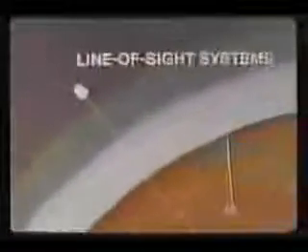For example, the operating characteristics of modern communication satellites are similar to those of the radar system already examined. Because of this similarity, their operation may be degraded by similar nuclear phenomena. The satellite uplink is somewhat less vulnerable to absorption than a radar of corresponding power because the satellite uses direct rather than reflected energy. The downlink, on the other hand, with low available power, requires very sensitive receiving systems with large antennas and low noise receivers.